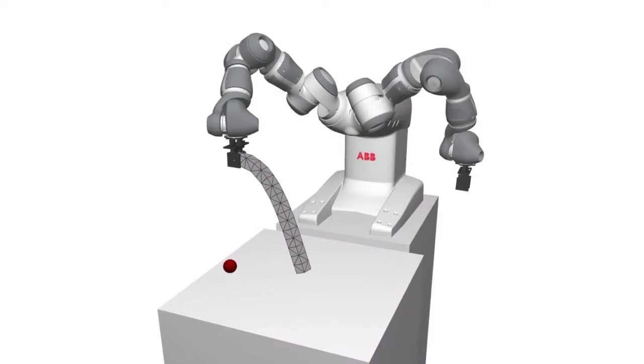We formulate this problem by modeling the elastic objects using the finite element method. In brief, FEM considers a discretization of the manipulated object into a volumetric tetrahedral mesh. The positions of all mesh nodes are assembled into a vector x_i, which constitutes the state of the object at the specific trajectory step i. For more information about FEM, we would like to refer you to the paper.